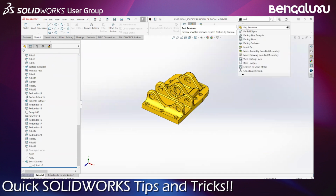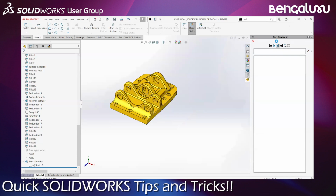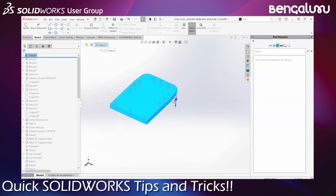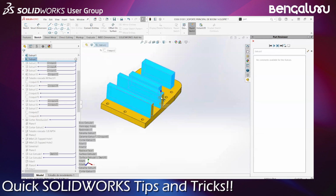Most of you might not have explored it, but once I click on this, you get these buttons here. So the first step is, see it says step forward, jump to end. So I'll start with step forward, right? See, this starts with the first thing. Like this is the first step, and you can see that all the dimensions that are used in creating this are also highlighted. So when you do the same thing from the feature manager tree, you just see the features, but you don't see the associated dimensions. But when you do the same thing from part reviewer, it shows you the feature and also the important dimensions for this, like 154.